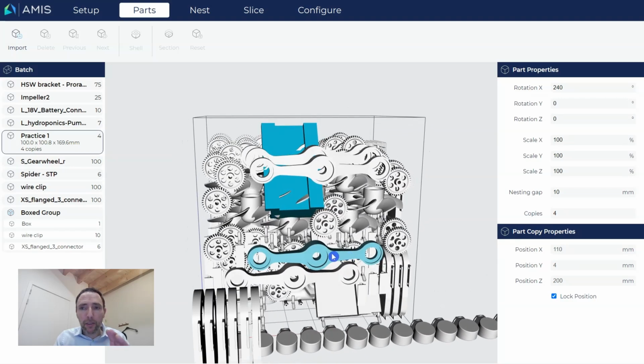So that allows you to quickly lock the position of your parts inside your build box, and you don't even have to remove all the parts for that. You can just keep on working on that. Now, of course, you shouldn't forget afterwards to re-nest, but since the nesting goes so fast, that's definitely not an issue, because also our nesting algorithm does not check for collision of parts, basically because it's impossible.